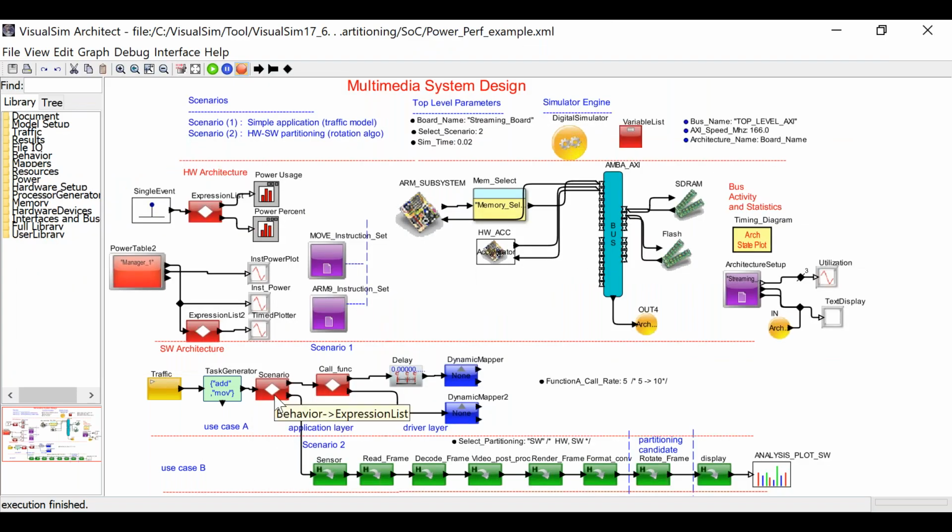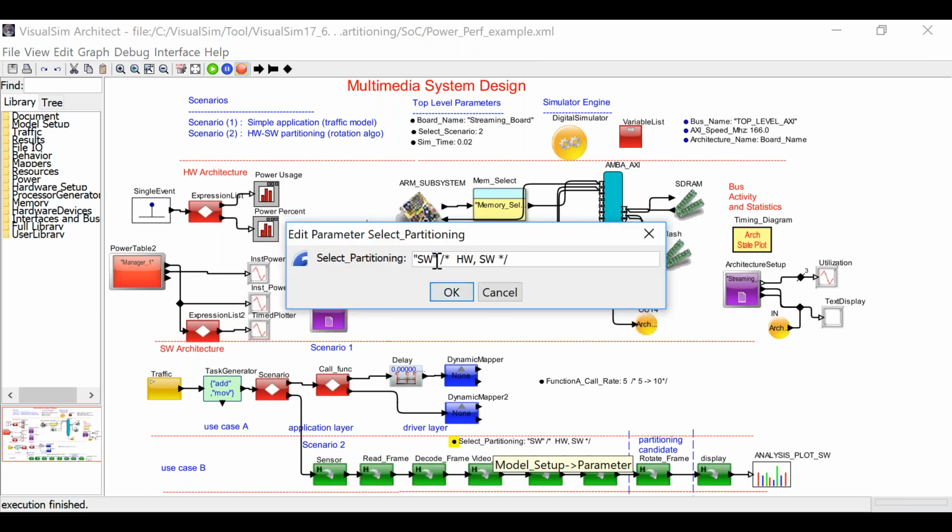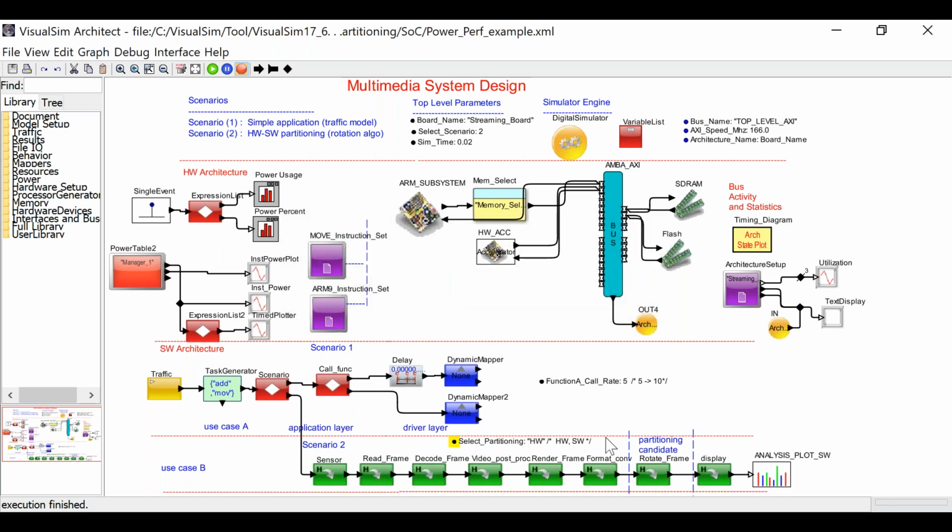So now looking at some of the other statistics, I noticed that this one here is the biggest consumer of the processor. So what I'm going to do is change the setting here to say that rather than running in software, I'm going to run this alone. Everything that runs in software, this alone is going to be moved over to the hardware accelerator over here. Same design, no difference. The only thing is now this one alone is going to be running on this hardware accelerator.